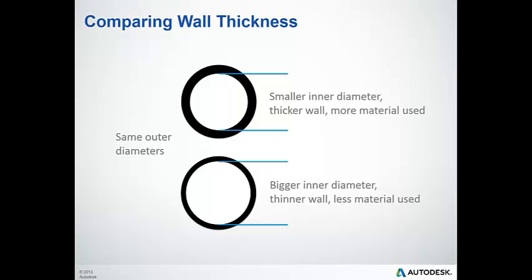The aluminum handlebars for a standard road bike, like the one used in our bike, meet all of these criteria. So, if we want to use a stronger material, we won't have to use as much material as the aluminum bars. Since the outer diameter of 25.8 millimeters will work for an adult human grip, we can make the handlebars thinner by increasing the inner diameter. The math of determining how much thinner is not covered in this presentation, but if you're interested in material strength, you should research tensile strength. The inner diameters we'll use for the aluminum bar is 17.8 millimeters, for the titanium is 22.5, and for stainless steel is 15.6.